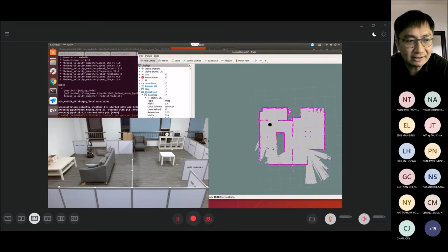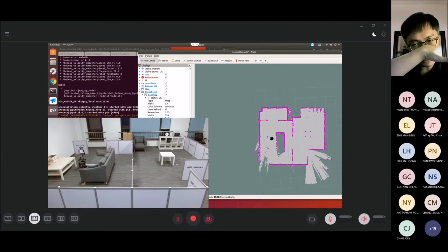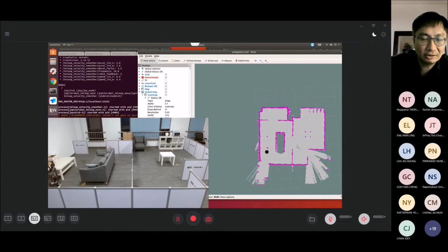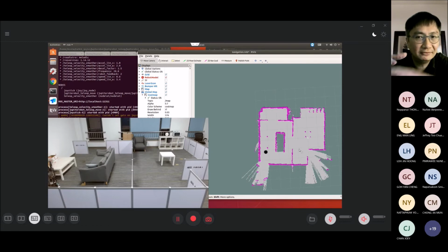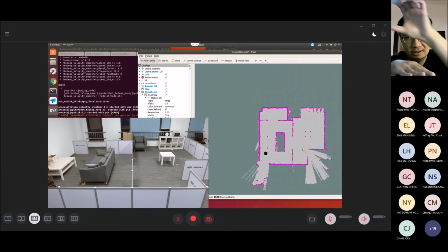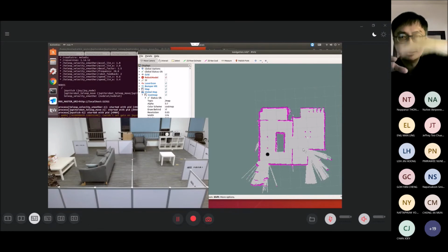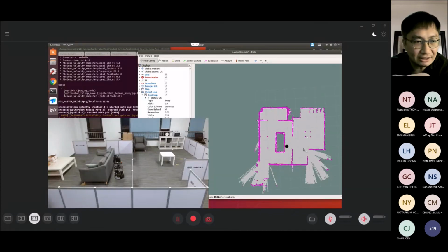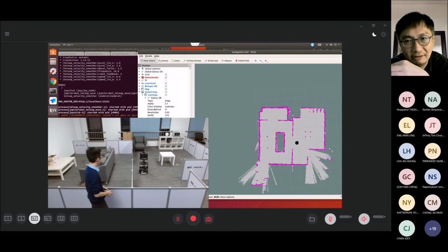It's the same reason I said just now: the laser scan basically is at a certain level, so it's just a 2D plane. If you are scanning a table whose top is higher than the sensor, then you can only see the legs. So the white table actually does not appear, but you can find 2 dots over there, right? The 2 dots indicate the 2 legs.